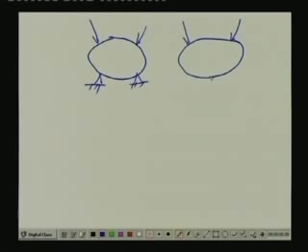Now, is it the free body of this whole diagram? No, this is not the right diagram. The right diagram will be, if we take the body acted on by the active force, and also at the support points you have the resistive forces which keep the body in equilibrium. Then this is the true free body diagram of this particular body.